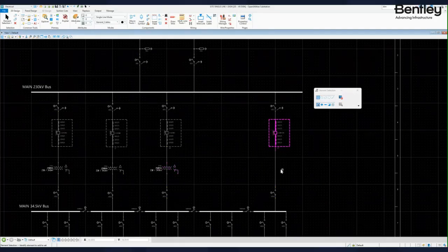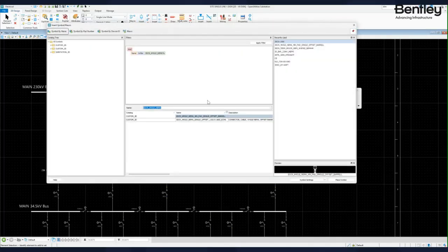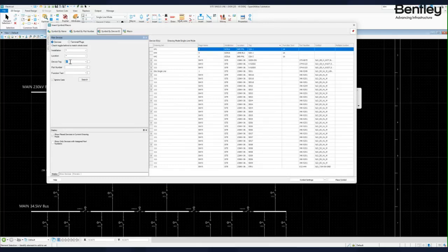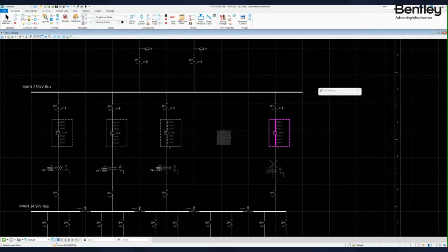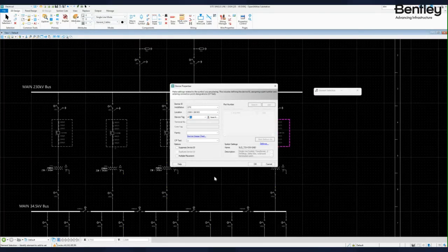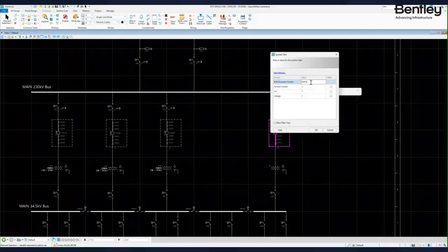I will, for example, at the very beginning, I showed you how I can use the device ID if it comes to my circuit breaker, but I can do exactly the same if it comes to the 3D models. That means that if I first inserted the 3D model, just like with the transformer, I can simply go with device by ID here and search for this here. And I have my transformer, place the symbol. I can place it right here. It will be associated with my transformer. Click OK. Boom, revision, everything.